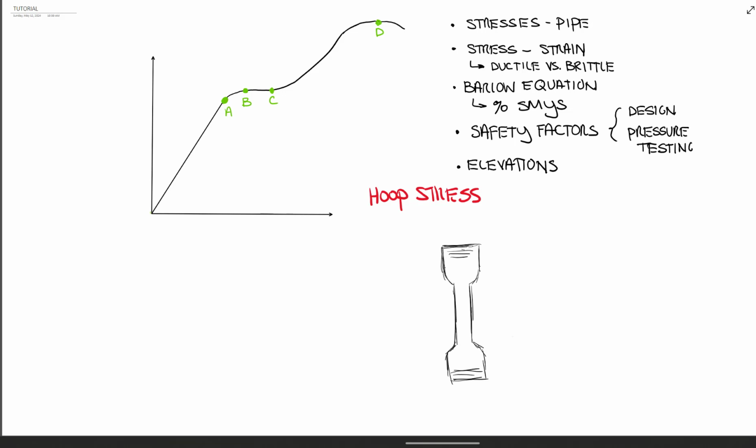Now, a way they traditionally illustrate this point, and maybe some of the welding inspectors watching this, like I said before, they go over the stress strain diagram, and I'll get to that briefly. But the way they determine if a material is ductile or brittle is they get a sample, a tensile sample, being shown below here, and maybe they mill it down in the center here and round the edges, and then it's threaded on each end, and they'll put this thing in a vise on either end, and apply a load and pull this thing apart. Before they do that, they will put two little dots here, gauge marks. They'll pull on this, wait till it breaks, and then come back and measure the final distance away before it broke.